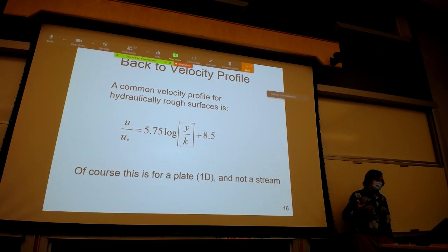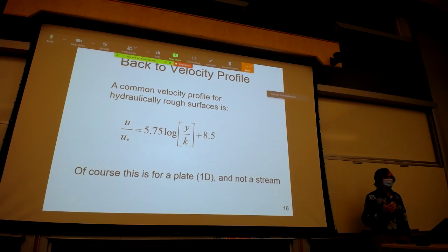And once we know the shear velocity, just like we did along flat plates or even in pipes, there's a velocity profile that you typically have in open channels. What you're seeing here is the turbulent velocity profile on a flat plate. If you recall, I gave you a handout all about development of the boundary layer. The handout was called Boundary Layer Theory, and this was the turbulent velocity profile for flat plates. The velocity profile in real open channels looks very similar to this.